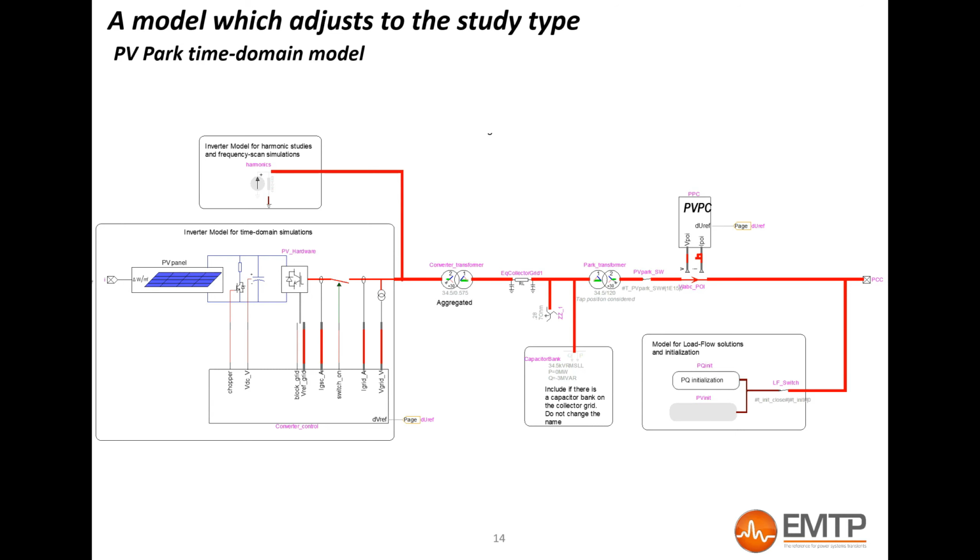To finish, here you have the solar park model. Only difference compared to the full converter is that we don't have the machine side converter. We directly have the PV connected to the DC bus. It's possible to have a DC boost here to adjust the DC voltage between the PV and the turbine DC bus. And again, I repeat, the control here will be explained in another video.